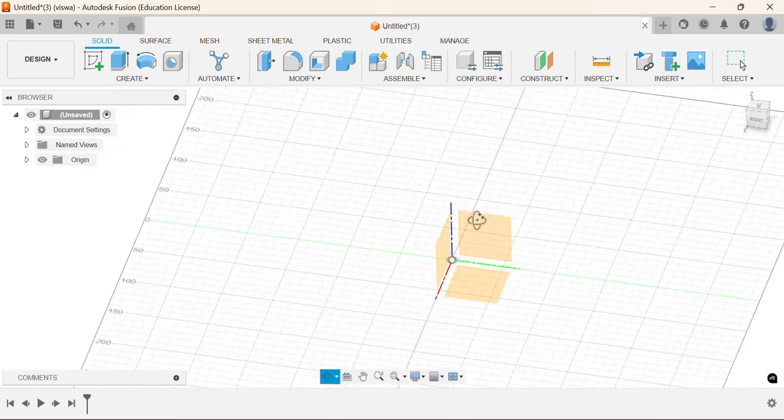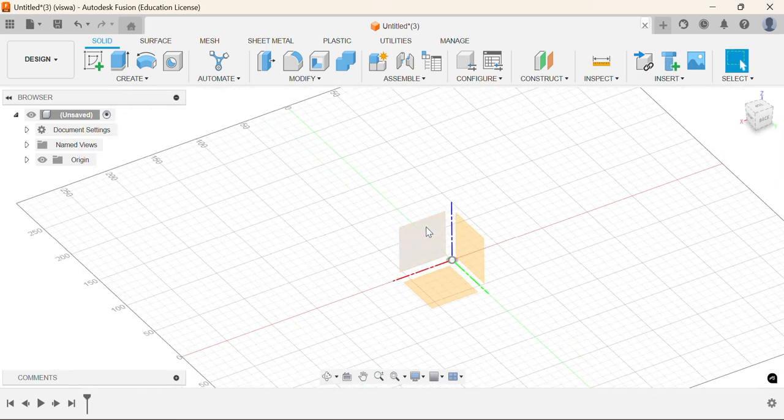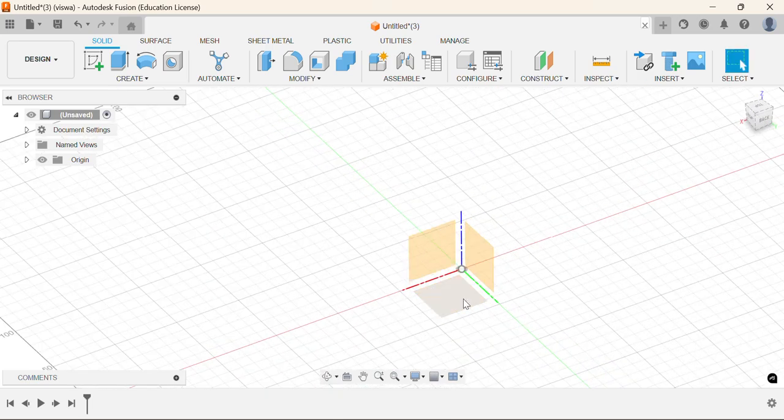Now if we see the interface in the local coordinates, we can see three planes, but these three planes are perpendicular in nature. Meaning if I take the xy plane and yz plane, these two are perpendicular in nature. If I take the xz plane and xy plane, these two are perpendicular in nature. In this case, the loft option will not work. Now if I want to operate with the loft option, I need to have parallel planes.